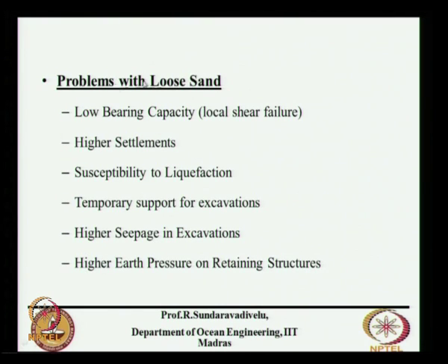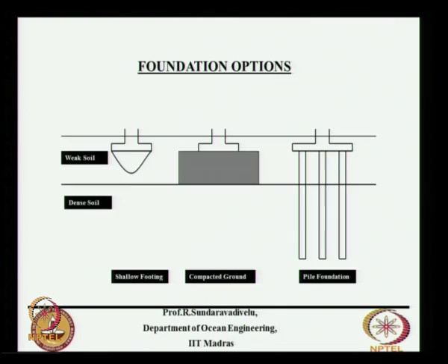So these are similar problems with loose sand: low bearing capacity, higher settlements, susceptibility to liquefaction. Then we need a temporary support when you want to do an excavation. Suppose you want to do an excavation, then you have to provide temporary support, then there will be very high seepage also, and there will be large earth pressure on retaining structures because of low angle of internal friction value.